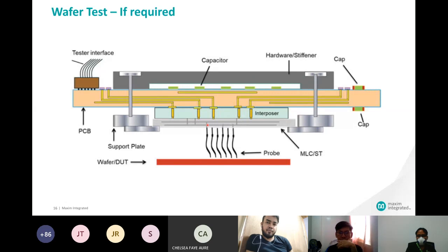And we have a roadmap, and we tell the vendor, hey, in the next 3 years or 5 years, I will have a 20 nanometer process, and the pad size and the pitch is this much. Make sure that you start your research now, so that in 5 years, I can buy the probe card from you. So that's how it is happening right now. We work with our partners.